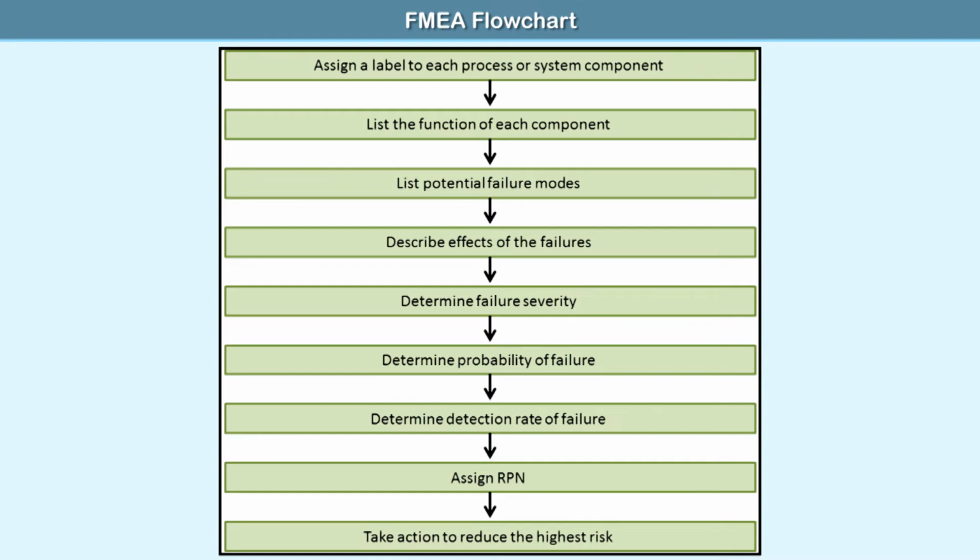Develop a block diagram that shows the components or steps and indicate how they are related. List the failures that may occur with each function. This is the failure mode. Determine what the ultimate effect of the failure will be.